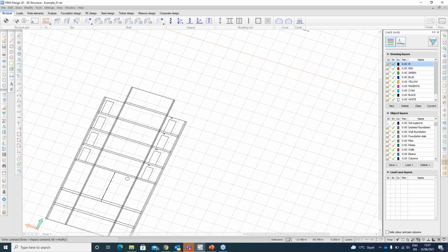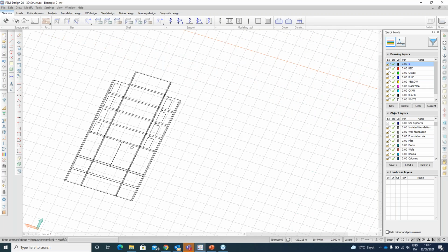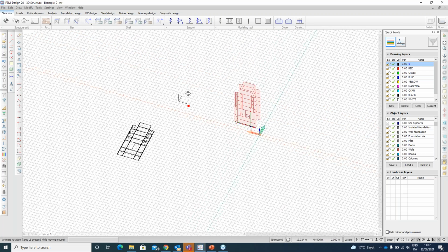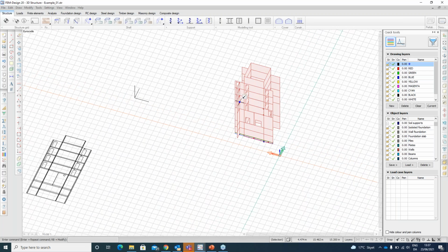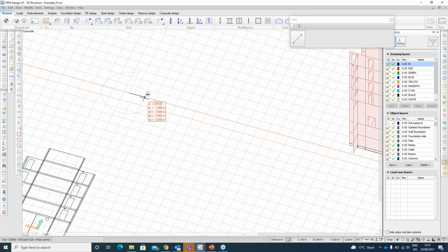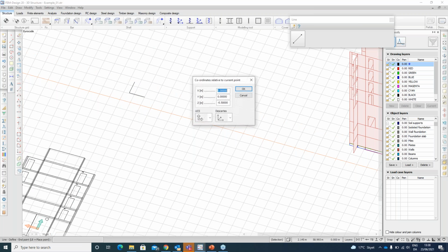I have the 2D drawing imported and it's on the horizontal and I want to flip it vertical so I can apply it to my walls and have a better view. Well, I can use the rotate function. I'm actually going to need, let's do this from the beginning, a line for orientation and axis. I'm going to just draw them in all directions.